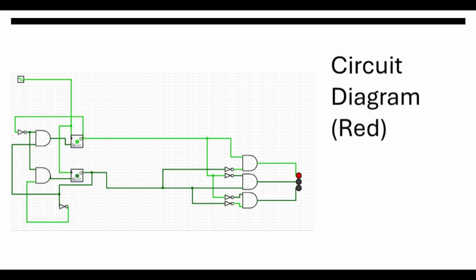In the final state, or red state, the first flip-flop output will be 1, and the second one will be 0. Our circuit now has a 1, 0 output. We can see that the gate of the red light has the first output as is and a NOT on the second output. Since we have 0 in the second, it will be 1 and the red light will run.